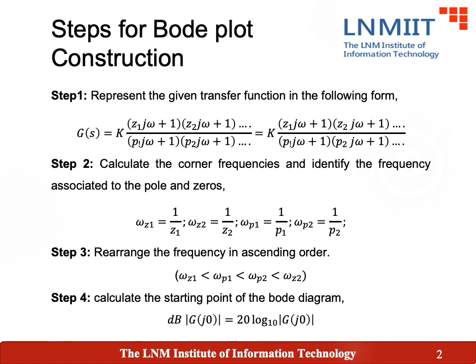Before sketching a Bode plot, let me give you a brief step-by-step instruction for construction of a Bode plot. Step one in Bode plot construction is to represent your transfer function in the given form, where all the coefficients come together with the j omega and the other value should always equal 1. It will make it easier to plot a construction and also help simplify your calculation. Okay, so next, step 2, find out the corner frequencies.